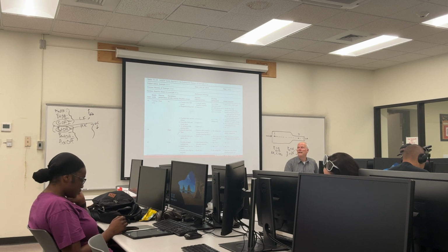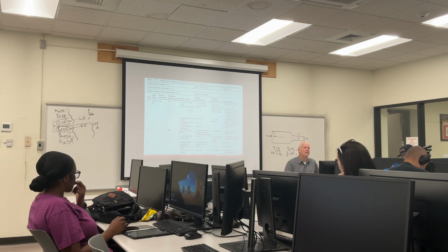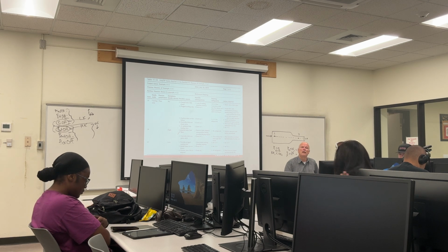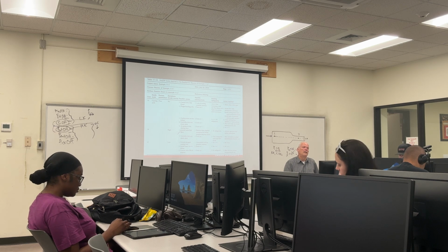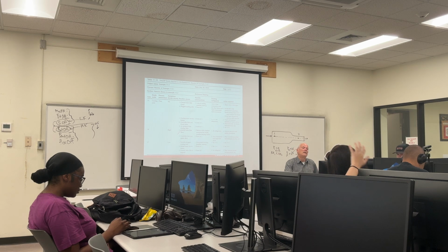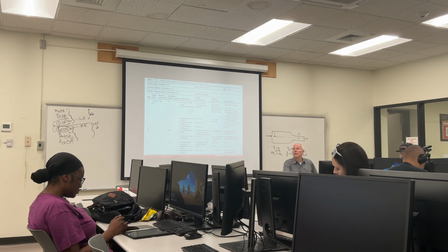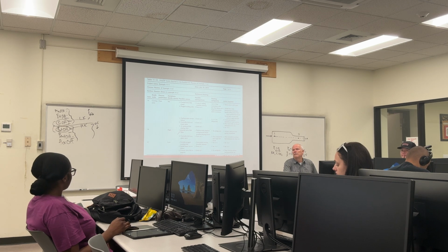No flow is bad, leads to runaway, and these are the possible things that we've come up with that would cause that to happen. And then we say, well, what safeguard do we have? Well, we have a flow transmitter, we have a low flow alarm, we have a high temperature alarm on the reactor. Okay?